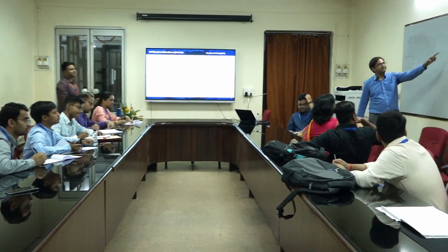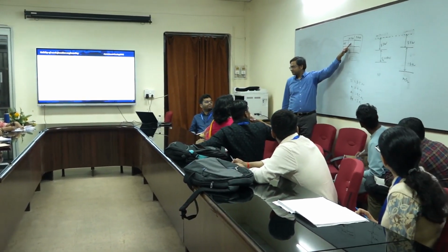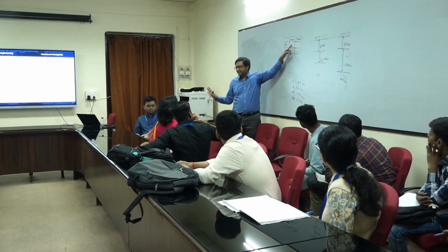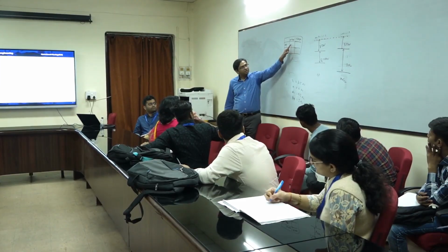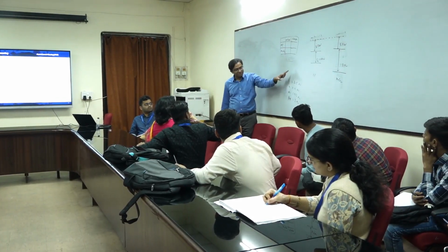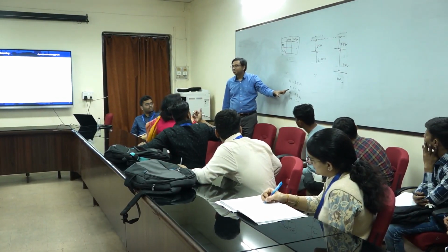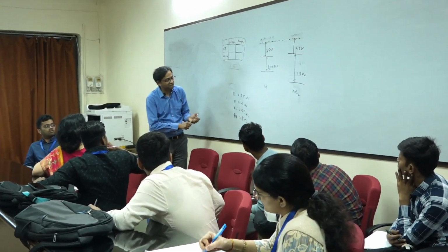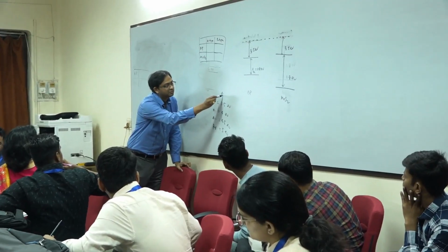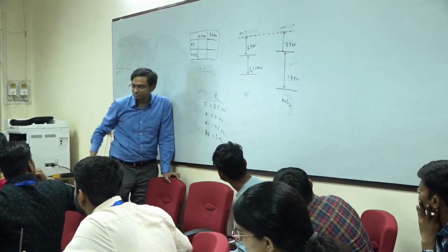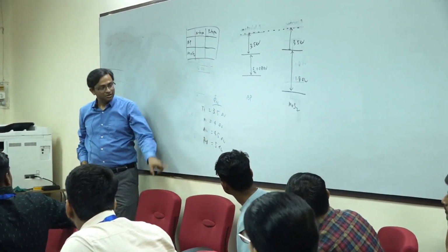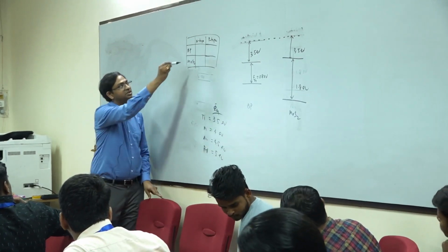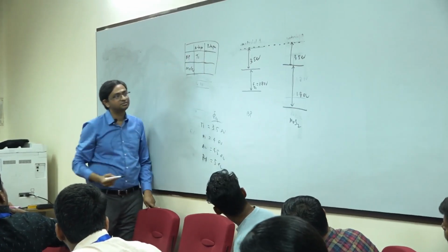Black phosphorus N-type FET, correct? So I want a Schottky barrier which should be 0 or negative, right? So which metal should give me that? No, gold is going to give me a difference. So these are the phi m, right? So we will choose titanium, correct? So this should be a titanium contact.